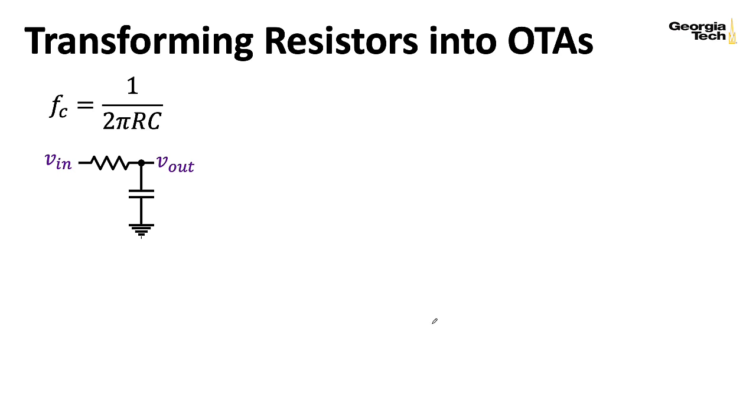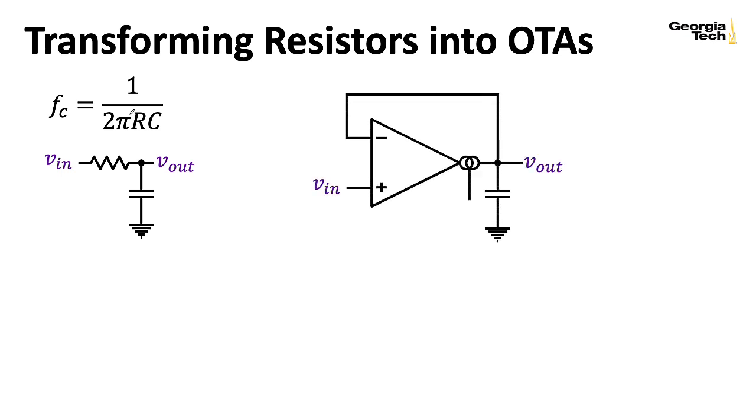Now we have a half-power cutoff point of 1 over RC in terms of radians per second. Of course, musicians don't like thinking in terms of radians per second, so we divide by 2 pi to get this half-power cutoff point in hertz. Now, let's play a game.